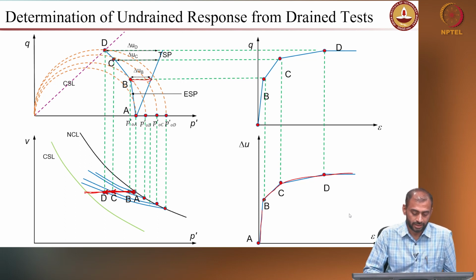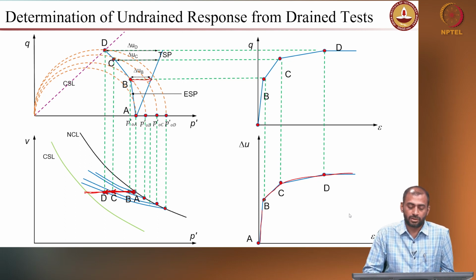So it's a useful model to predict the material response, and it is one of the commonly employed models in any finite element framework, where you can input the appropriate parameters and solve complex boundary value problems, right? So that's the discussion on the original Cam clay model, modified Cam clay model, and how it is used to predict the material response.